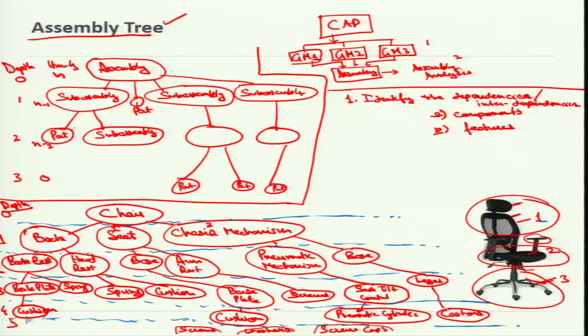Now, considering the creation of, let me say, the base of the chair that has 5 legs, and each of the legs has an assembly system or a small component, and at the end of each leg we have a screw hole where we try to add the caster or the wheel. We can create holes as separate features and then create a pattern of them, and we can create only one rim and create an array pattern of them. So, these are the features.